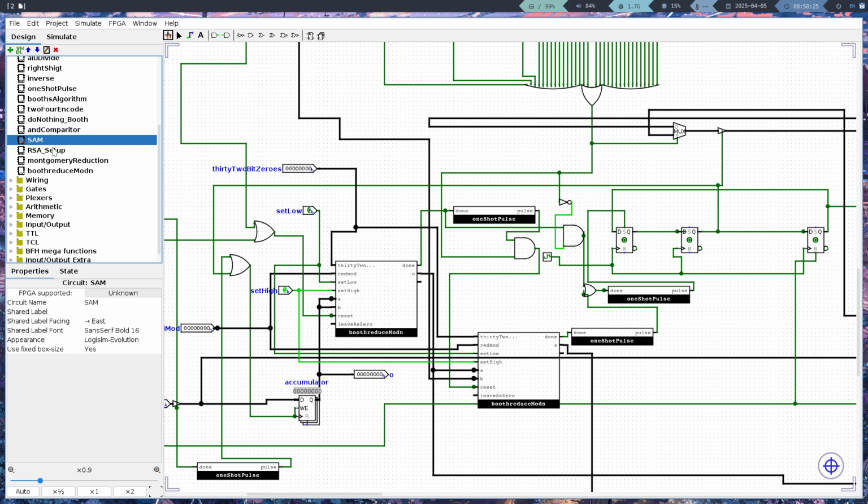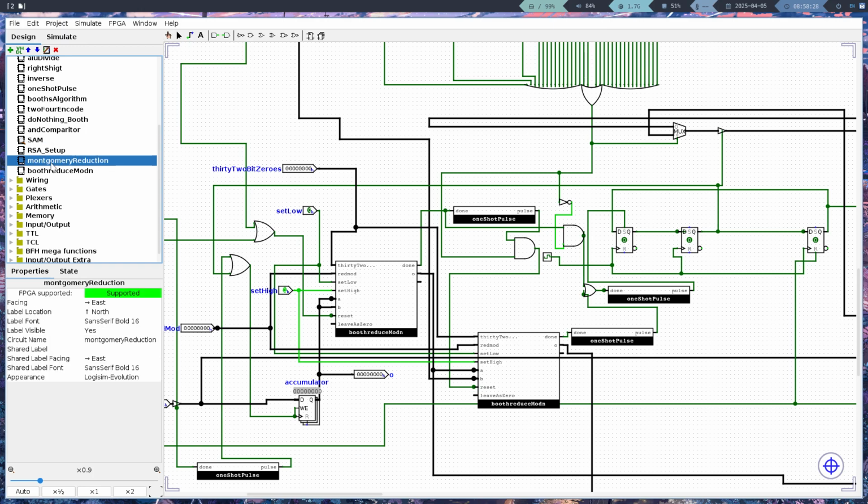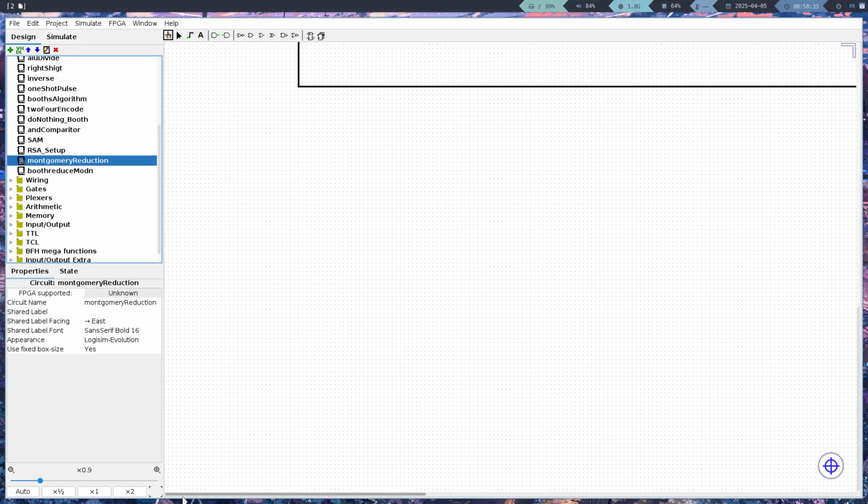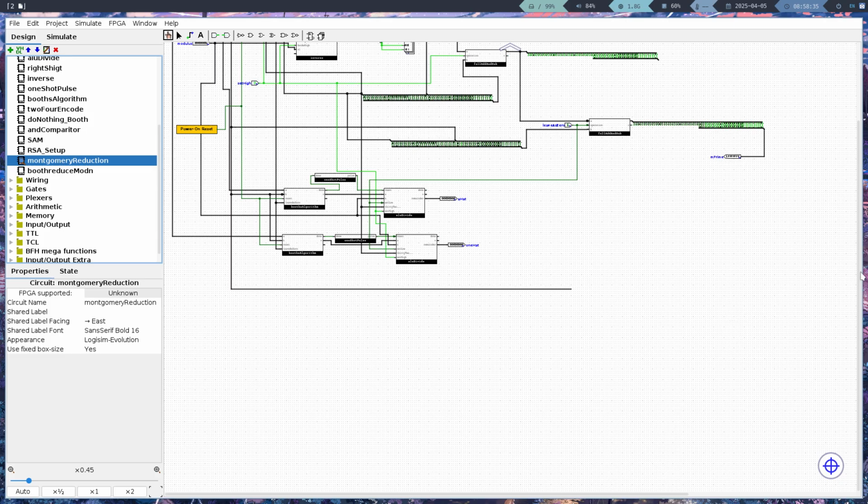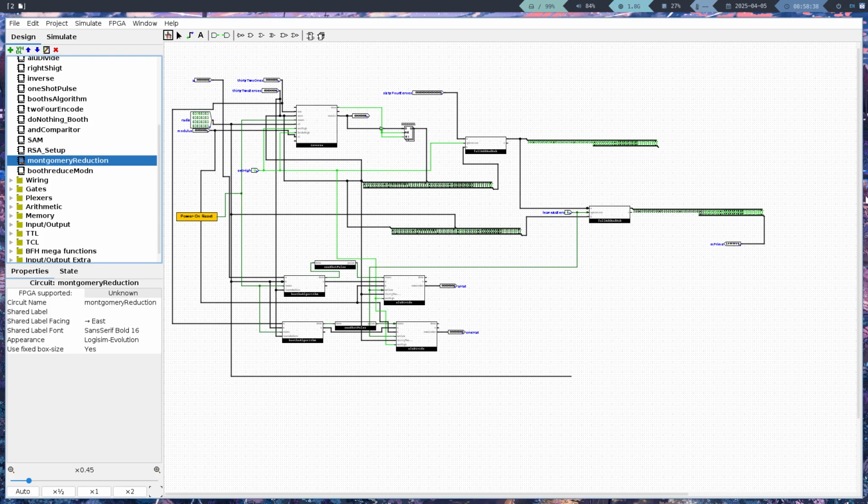And so there's a better way to do this, though, and it's called Montgomery reduction. And it's so cheap, because, and I didn't do this because I was going to take that and do it in the FPGA implementation, so this is sort of an incomplete version of Montgomery reduction. But basically what you're doing is you enter into this Montgomery number system. And the key to it is you have this radix value, which is 2 raised to some power. And what that allows you to do, as long as it's greater than your modulus, is convert these expensive division operations into simple right shifts.